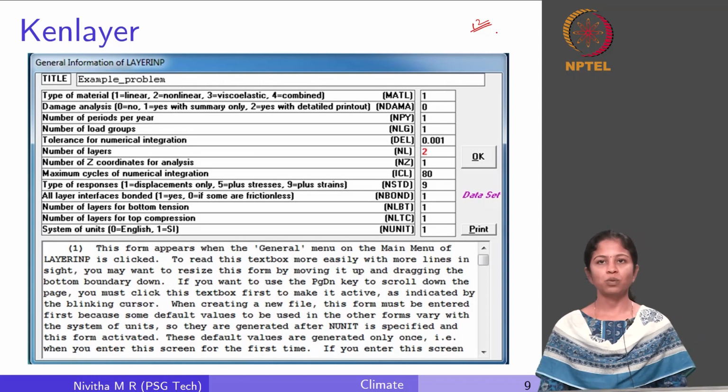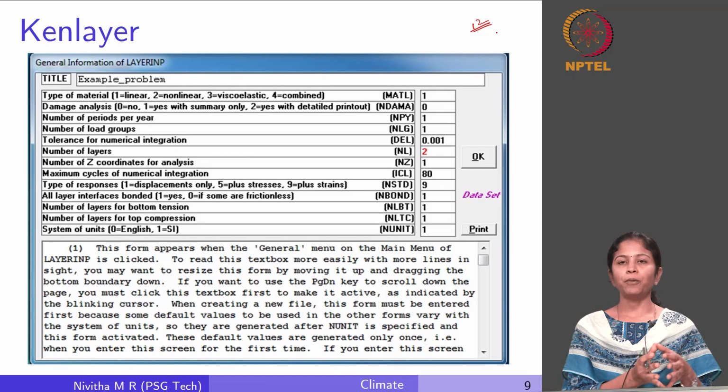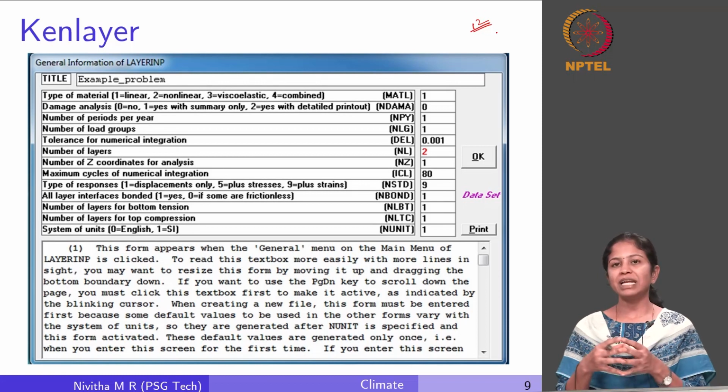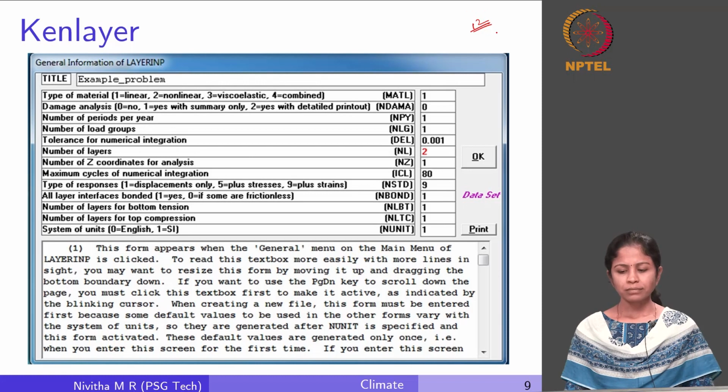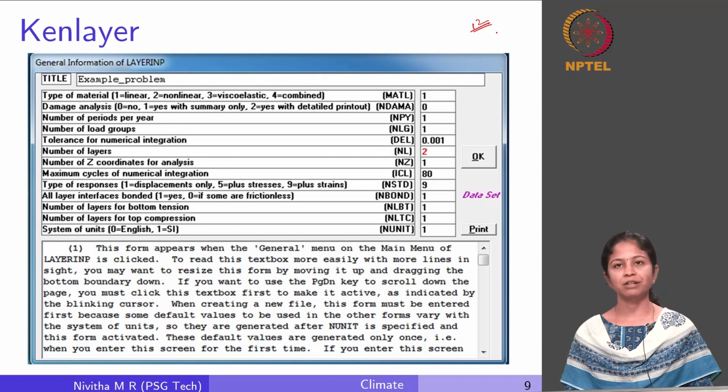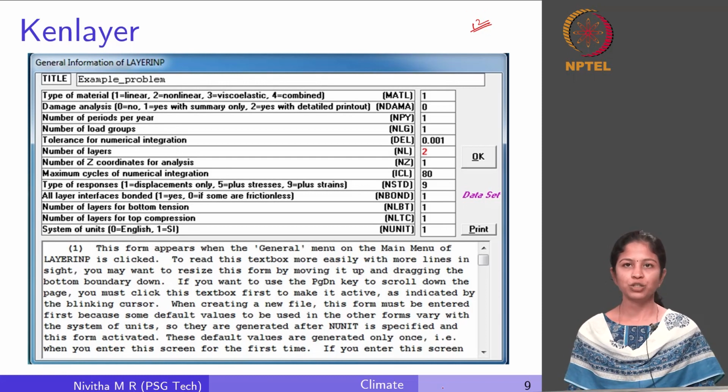So if I give period 1, it allocates a proportion of axle loads during period 1, and that particular modulus is used for computation of strains. So like that, for each period the appropriate modulus value is used for design. By default it is 1, wherein we just use one single value like we had seen before in IRC 37. The maximum that you can give is 12.